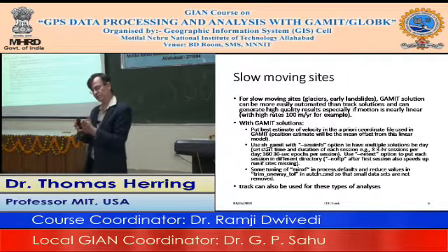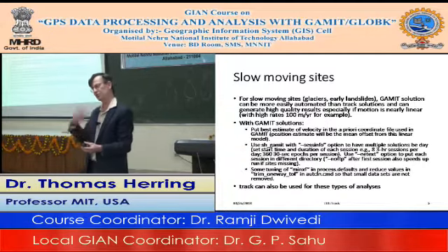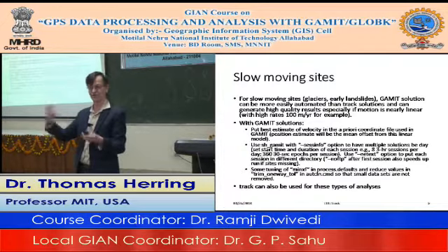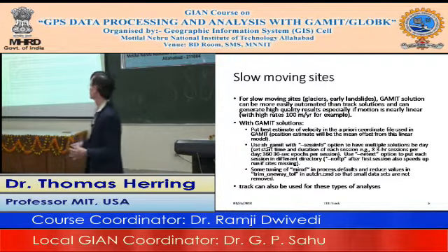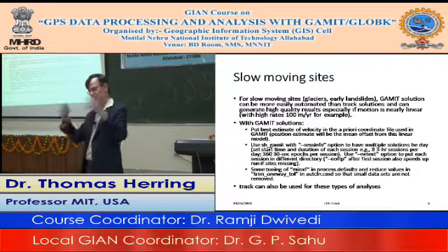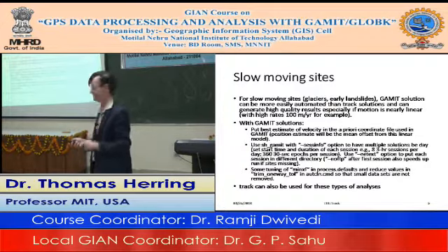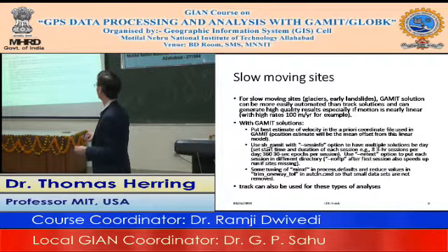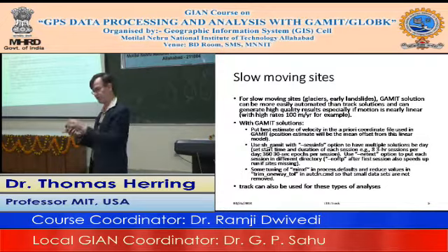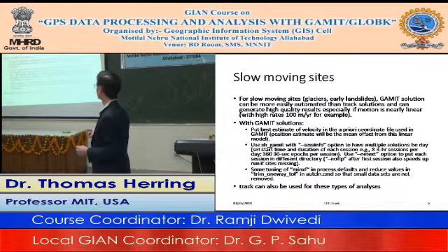But you can often also do it in GAMIT with short session processing. When you do it that way, it allows you to feed the results into things like TSView and other kinematic programs, like TSPlot, and so on. So you actually get access to a lot of good utility programs you can play around with. If you do have one of these cases, you might want to think about whether to do it in track or whether to do it with GAMIT in this sort of kinematic mode.